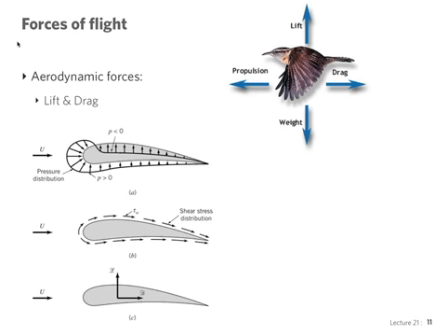So the aerodynamic forces of these four are, of course, lift and drag. Weight is just gravity, and propulsion will be generated sometimes by aerodynamic means and sometimes by other means, but the purely aerodynamic forces are lift and drag. So all aerodynamic forces are due to basically the integration of all shear stresses around the surfaces.